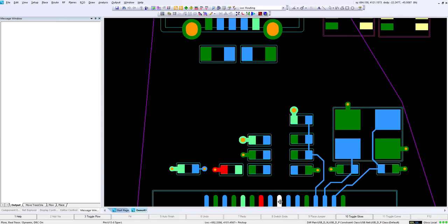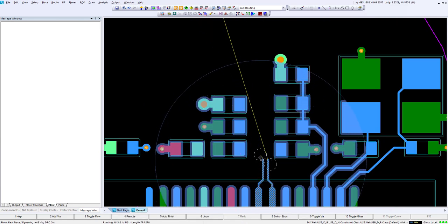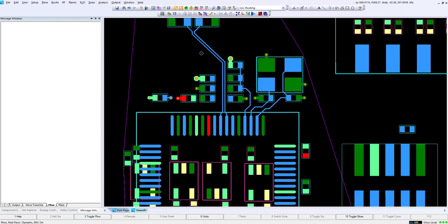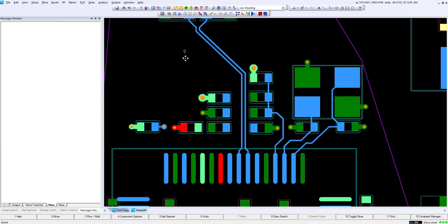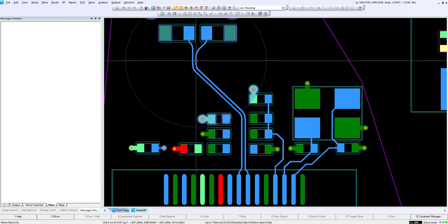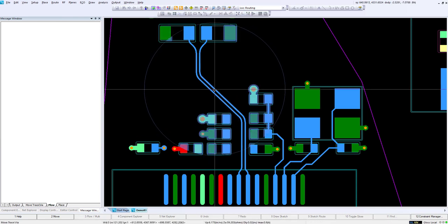In addition, there's been an enhancement to entering and exiting pins and vias. If we go ahead and route this differential pair real quick, we'll go ahead and add some arced corners and talk about diff pair modifications with arcs. So with our differential pair now having arcs on it, there's better control over the arcing of our differential pairs and modifications of those items.